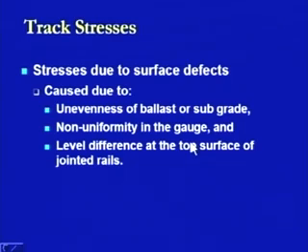So, another point as far as the track stresses is concerned is the surface defects. Now, these stresses may be caused due to the unevenness of the ballast section or the subgrade section. This is the lowermost section or the second lowermost section of the components of the track. If there is any unevenness in that section, then it may result in a certain amount of stresses.